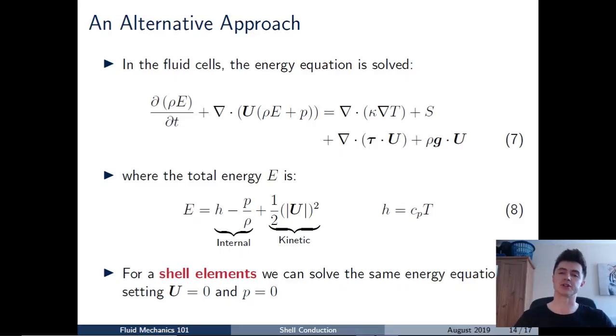And the reason I'm using the general energy equation here is, remember from my video on the energy equation that the flow may be compressible in some instances, and if the flow is compressible, there's going to be an interchange between mechanical and internal energy there, and so we have to solve for the total energy of the flow, rho E. And of course you can see there, if you examine the total energy variable E, you can see that the temperature is coming in through the enthalpy H there.